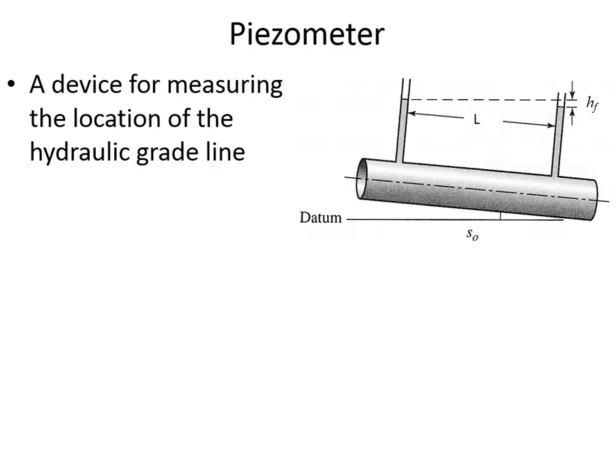You've seen piezometers before. You saw piezometers in the experiment where we were having the pipe contract. It was the Bernoulli's experiment. And you saw the water level decrease at the piezometers that were at the throat of the venturi. And then the water depth increased after the throat expanded again. And of course, the reason why the piezometer depth was decreasing was that in the throat of the pipe, the velocity was higher. And that piezometer was illustrating the effect that when velocity increases, pressure decreases.